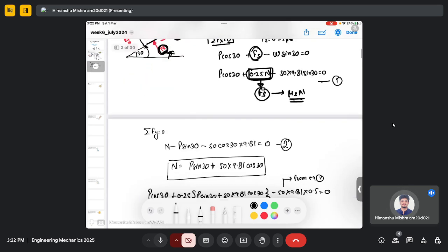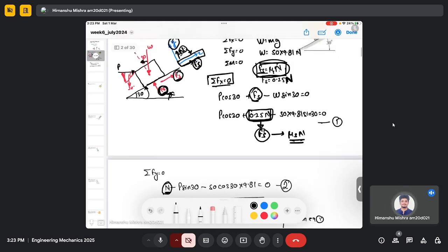And here in the second equation, you can see there is no friction force, because friction force is not in the y direction. So you will have the whole component of normal reaction force. So the normal reaction here, it's still due to friction only, right? No, no, no. So what happens? Let's say you have a body, and for now you ignore the effect of friction. The plane is smooth. So since this body is in contact with this surface, there will be a normal reaction force here.